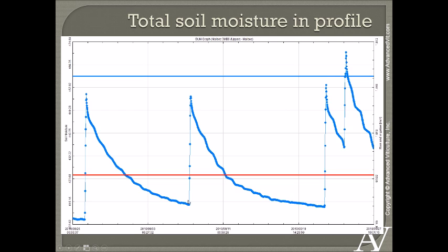So what we're seeing here is an irrigation followed by another quick irrigation. Again, I wasn't controlling the irrigations in this block, but it does point out some interesting things. You see that when it was irrigated, initially the water content dropped pretty quickly, and then it starts to slow down, and then it starts to really slow down. And so what we're seeing here is a progression in water stress. This is actually a fairly long interval, so it's kind of a bigger drink with a long interval between irrigations. I think we're looking at about 2 weeks between irrigations, and this is that same soil, a fairly shallow, about 32 to 36 inch deep soil overlying rocks.